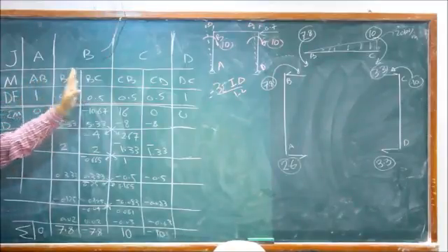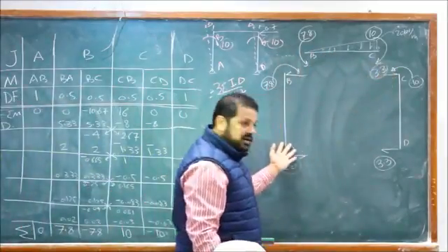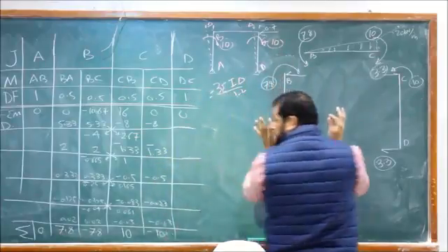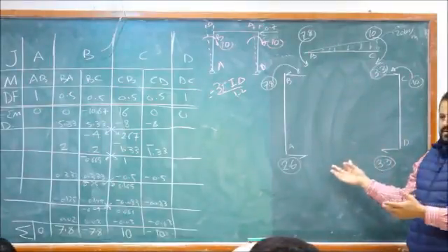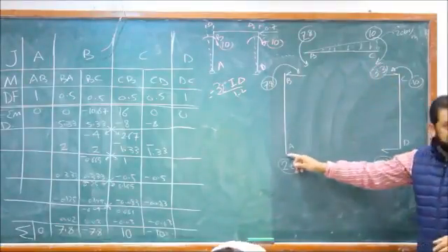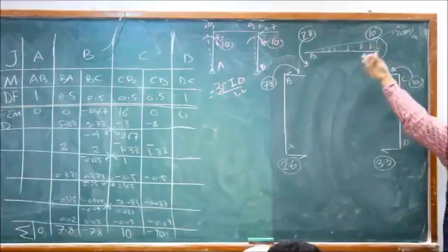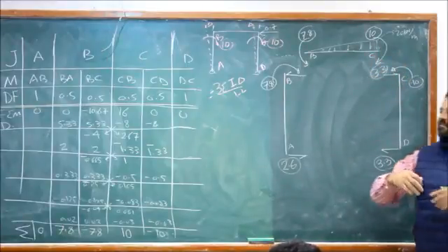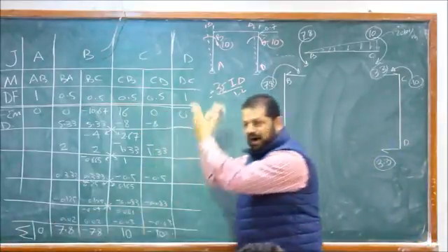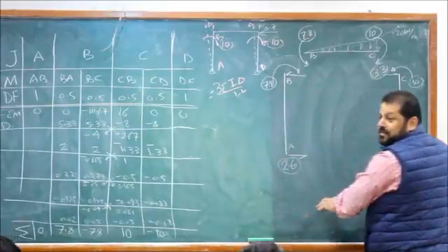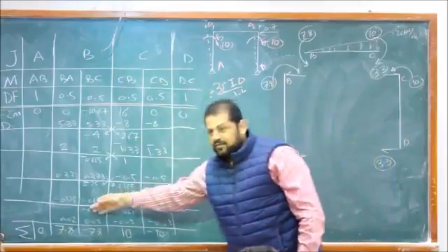So we assume 10 here. We will calculate these moments here, the end moments, exactly this and this and this and this and this one, based on the 10. Then make your solution easy. Good? 10. Then you calculate this and this. You add them. If they give you 1.7, good. If it's not 1.7, like for example 5, the moment that you will get by the 5 will be 1.7 over 5 times the values you get from the 5.